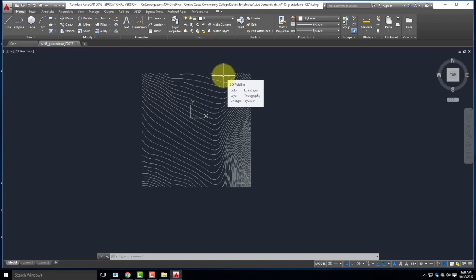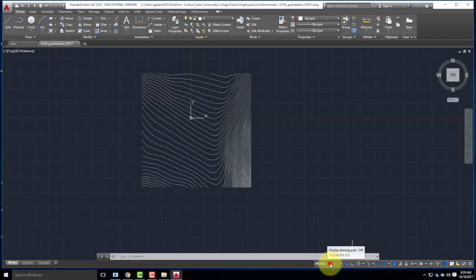Yep. In AutoCAD, you have the grid, you'd be in a different space, but now we're in a photography space with these lines as we're creating. Right. If you feel like you really need a grid, you can in fact turn the grid back on. There's a little button down here at the bottom for grid, and you can have the grid come back on if it helps you visualize. It's more a personal preference than anything else. You can also adjust the grid settings.